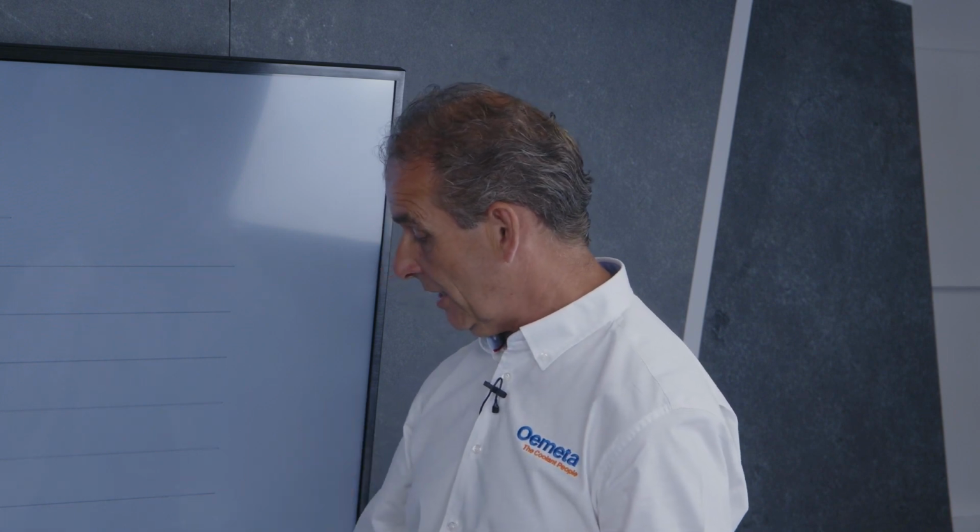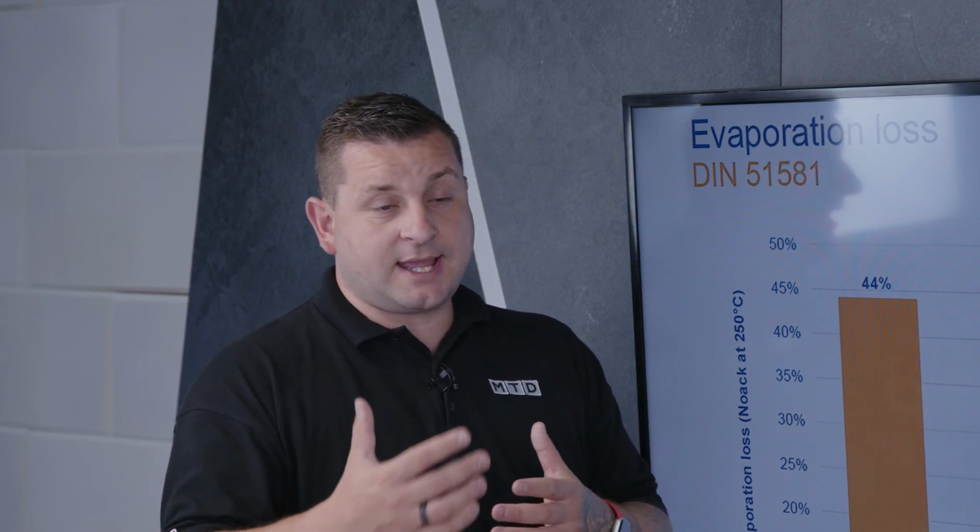So for companies who are looking for really high performance, low consumption, a really good flashpoint, then look for both the esters or the GTLs. And if you're looking for a real health and safety step forward, then look at the esters. It's got all four, and so I would seriously have a look at your oil process at the moment, because now is a great time to make improvements there. And then obviously the health and safety point is such a big point, because machinists who have been working for 10, 15, 20 years with oil, obviously you don't want that getting on your lungs.